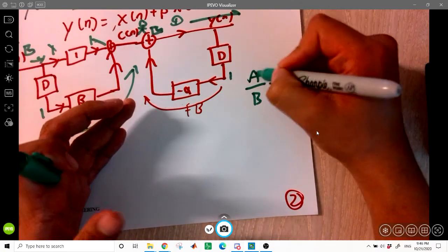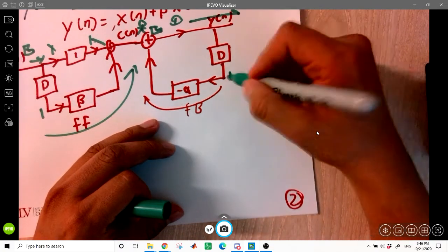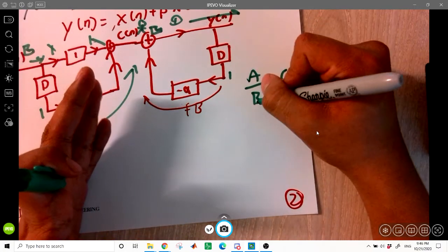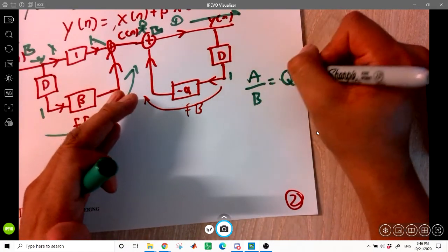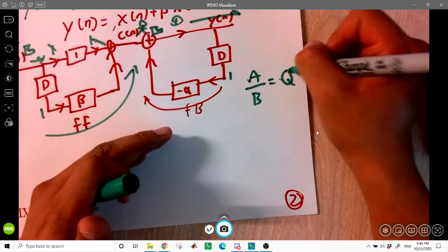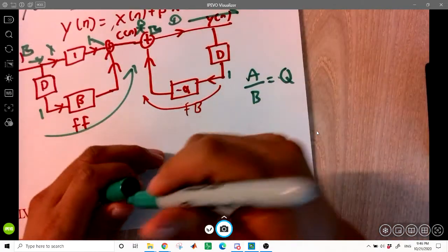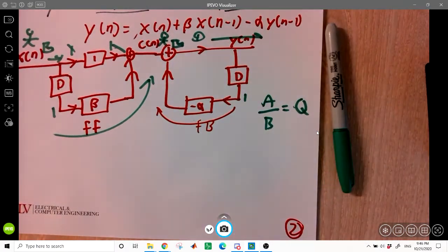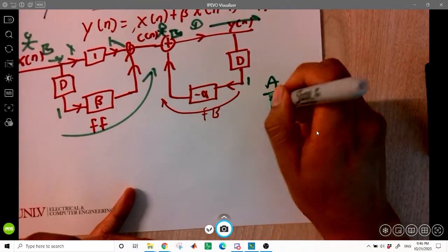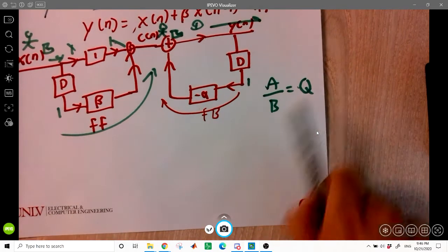You can just turn off your source. However, if you have your B term, the easiest way to go to infinity is if this goes to 0. That's really easy to build, which is not good for this. It becomes unstable, or your bits start saturating, or you get some conditions that you don't like, your op amp starts to rail to VDD or to ground. So this right here is what we consider our pole, and the A term is considered our zeros.